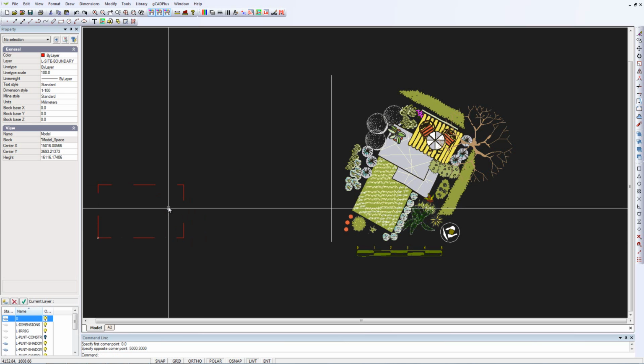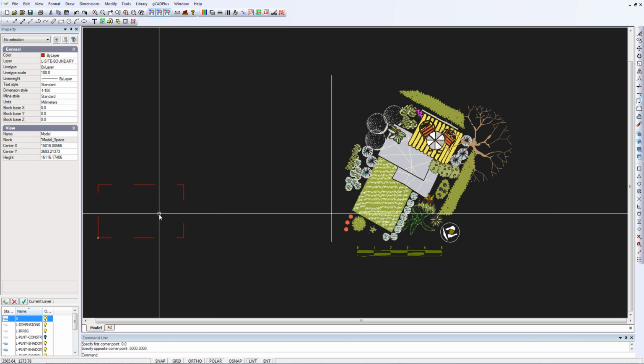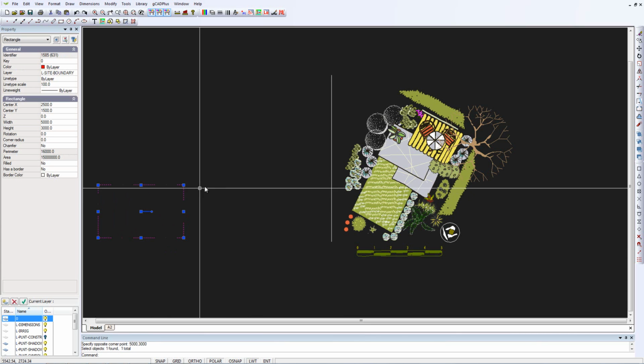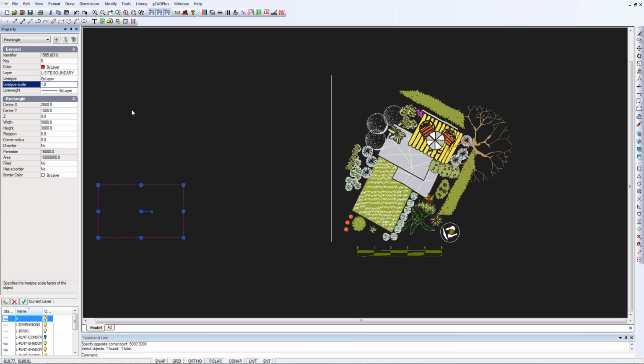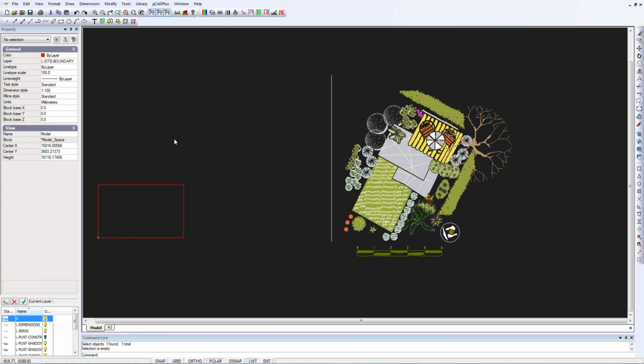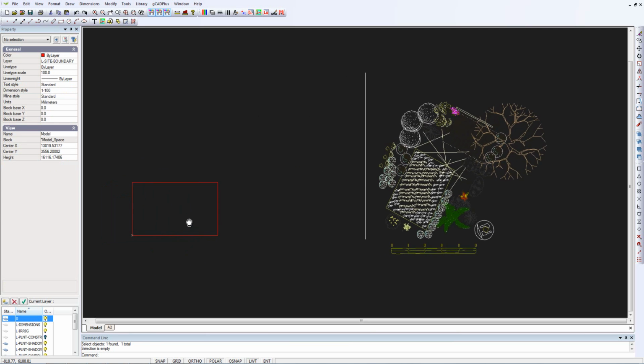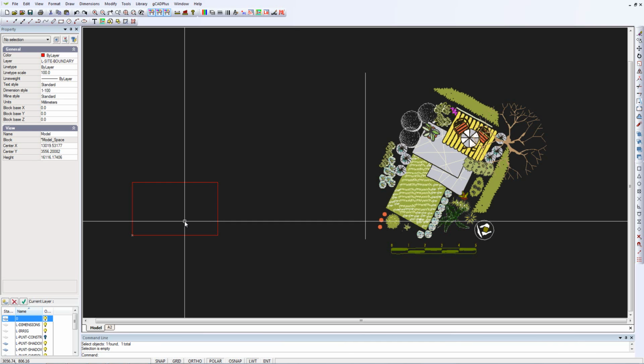But you'll notice it's got a funny line type pattern. We can fix that up in a couple of different ways, but for the moment I'll just select the rectangle, and I'll change the line type scale here from 100 to 1, and then unselect all and come back in. So there's our rectangle delineating our design space. Let's just move things, and I'm moving things by holding the wheel of the mouse down, keeping it down, and panning across. So what we want to do is put a little design in here.